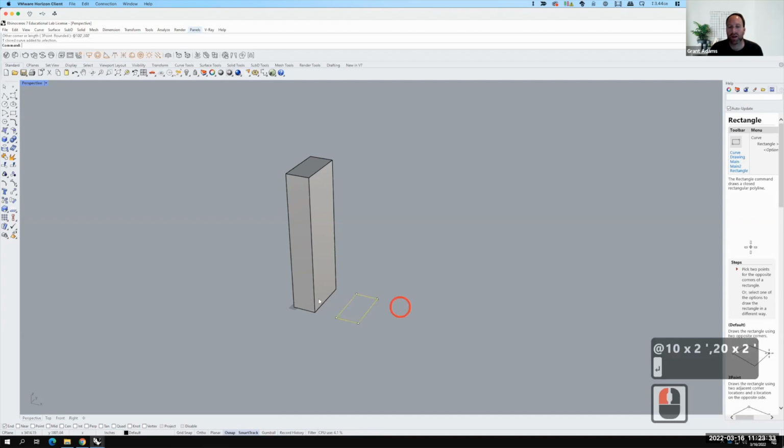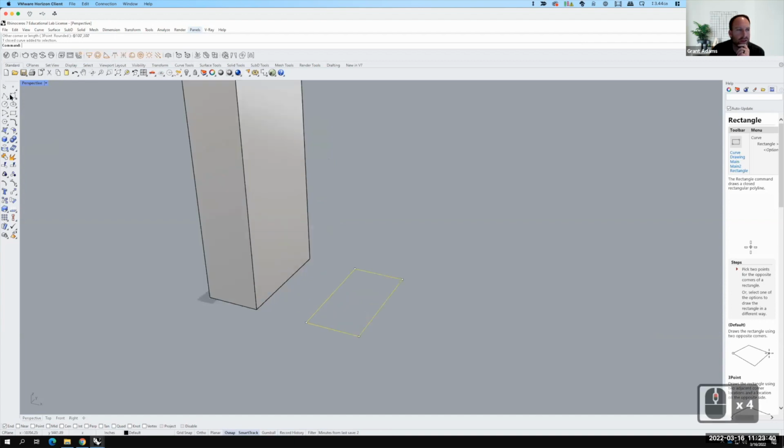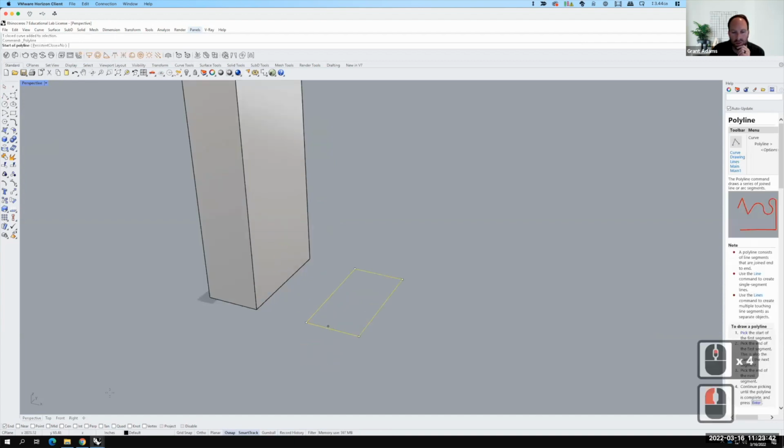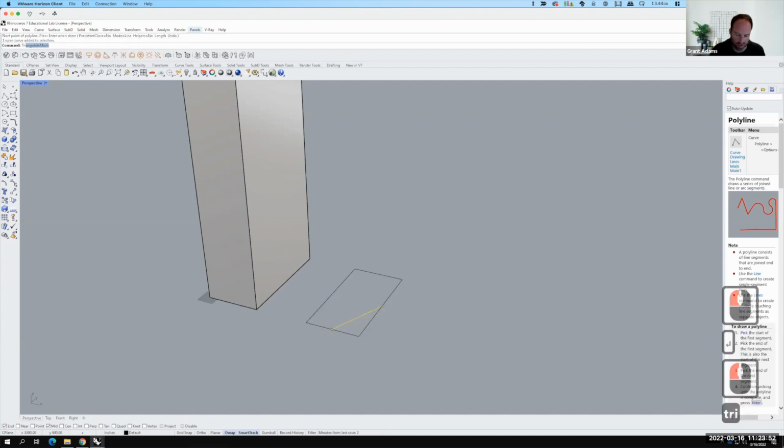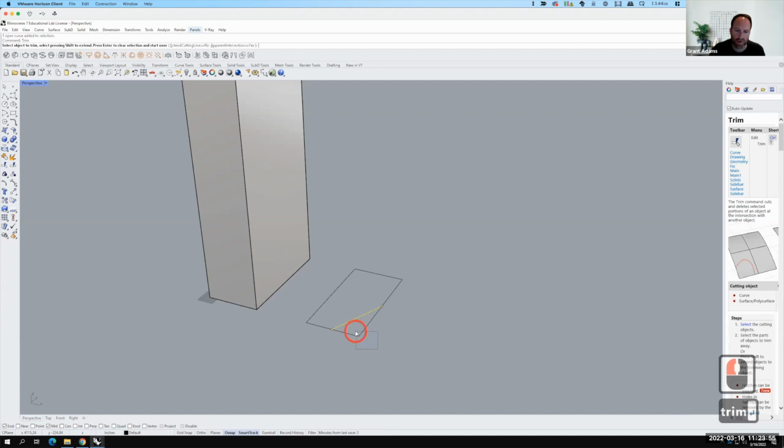And so this time, instead of doing a box, I just did a line here. So let's say that maybe I'll clip this corner. So let me turn on my midpoint snap here, and we'll go to there. And then I'll use this as a trim. And maybe I'll trim that off. So I've clipped that corner of the building.